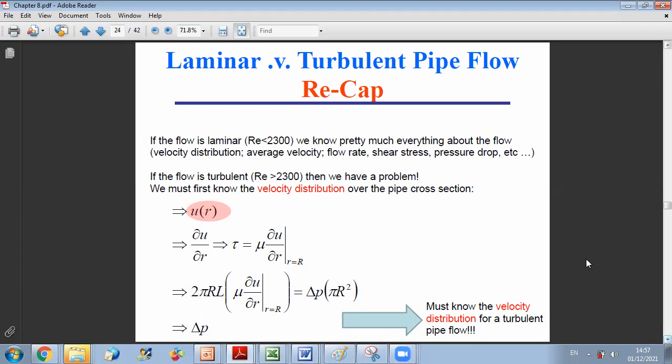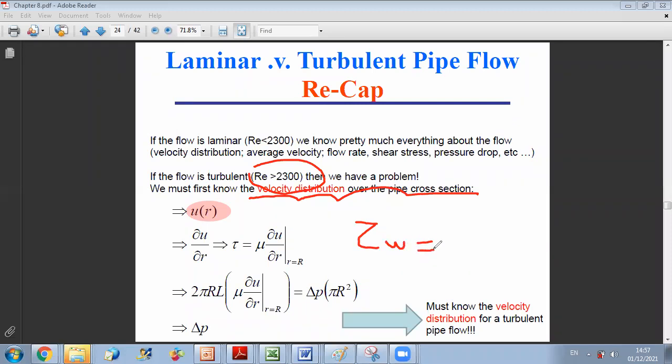So as we said, no analytical solution is possible for turbulent flow. Then we should try to experimentally find what the velocity profile is, and then the shear stress, because the shear depends on the velocity profile. So the technique will be to measure velocities experimentally, do fitting techniques to find an equation for the velocity profile, and from the velocity profile equation get the value of the shear stress. This is the technique that we will follow in the next step.